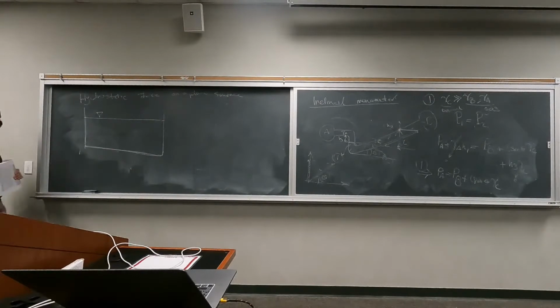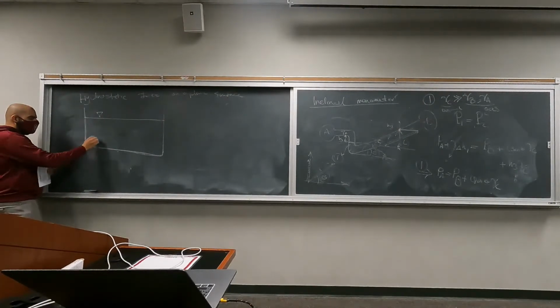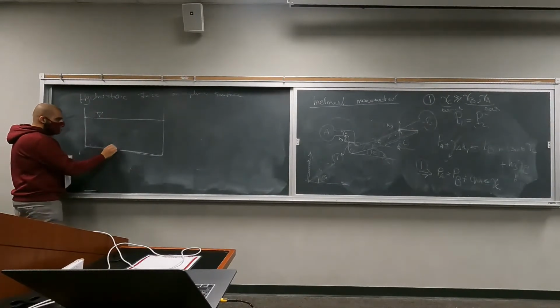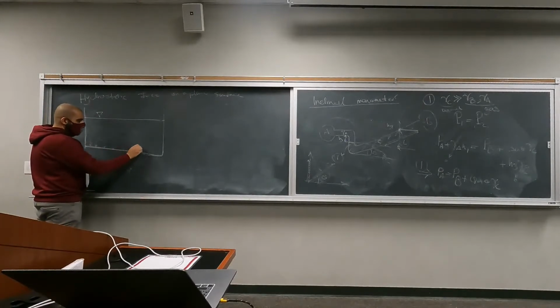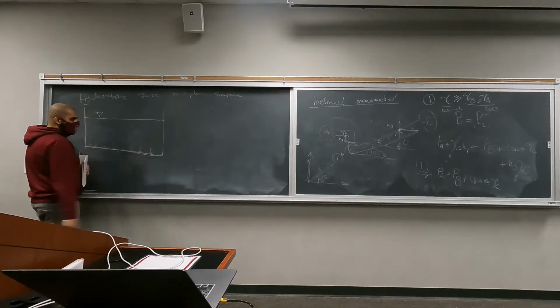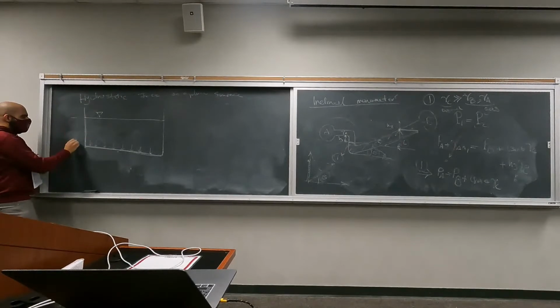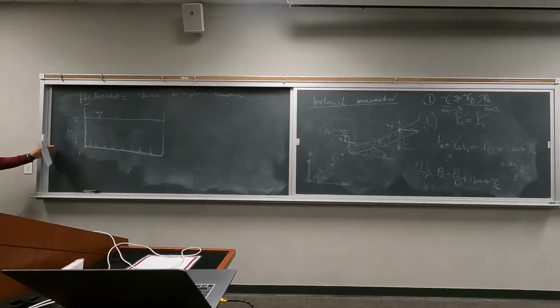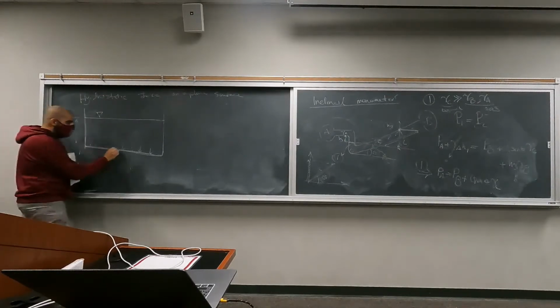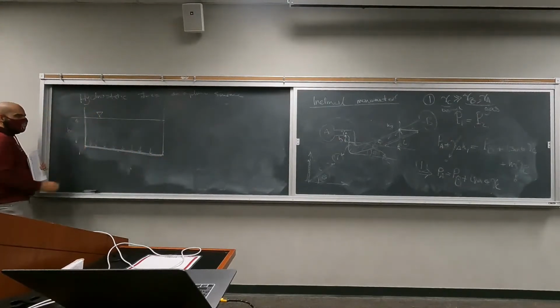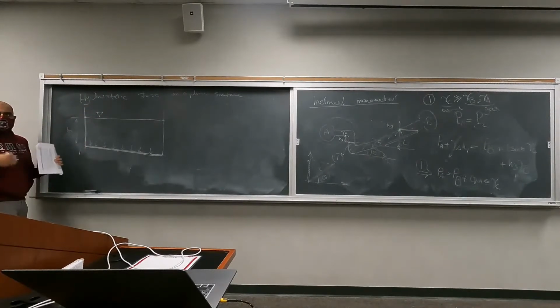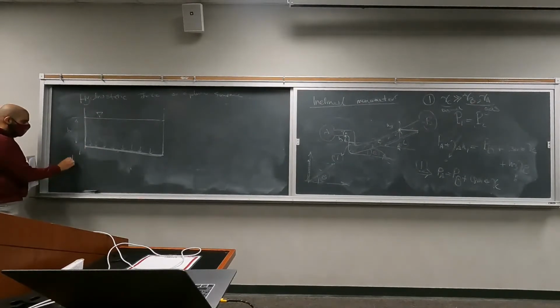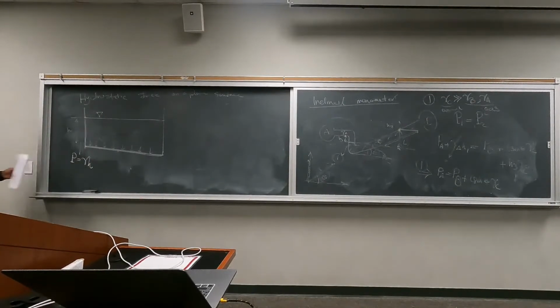Okay, we can find the hydrostatic pressure itself as a function of the height from the surface. As you increase the height, your pressure is going to increase. At the bottom, we are going to get the maximum amount of pressure because you have the maximum height, and that is gamma h, right?